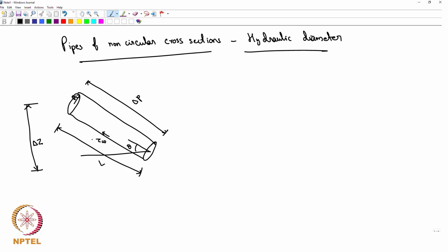So there is a pipe, and you have applied a pressure difference which makes it flow. It's inclined and therefore weight is playing a role, and of course the viscous friction is acting against it. So you can write down a pressure balance, which would mean that delta P into pi r squared